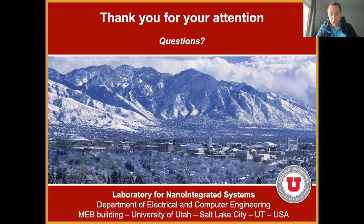Bottom line being, if we just look at the logic synthesis part, we evaluated what ABC can provide and what MIGs could provide, and MIGs do provide interesting performance improvements on two things. The first would be reduced number of LUTs and increased performance for arithmetic intensive benchmarks. We knew that. The second is that MIGs give you the ability to customize your architectures to support them